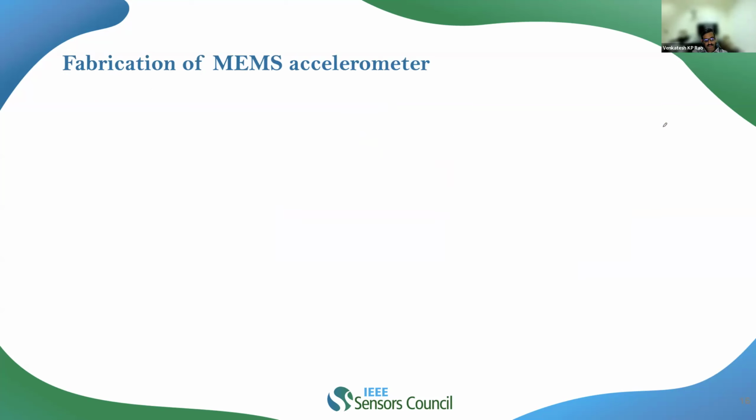Now, on the other hand, if you look at the automotive industries or anywhere, the accelerometers and gyros play a very, very critical role. So, to start, for accelerometers, since they are inertial sensors, we indeed require a larger proof mass under consideration. For the larger proof mass, it's not recommended to go with surface micromachining.